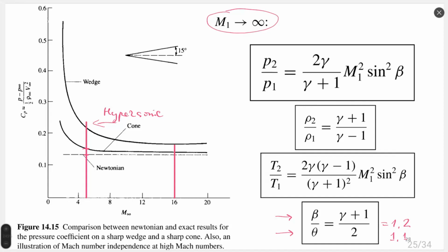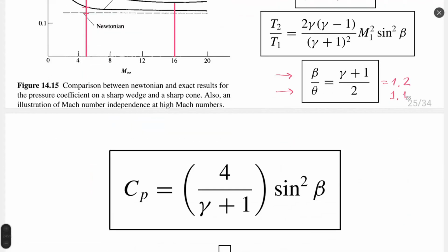So the angle of shock wave will be approximately 10 to 20% higher than the angle of the body. This is a very important observation. Once you calculate hypersonic flow, we understand that between 10 and 20% extra you add to a body shape, and you start to receive the shock wave. Shock wave will be between 10 and 20% of body thickness.